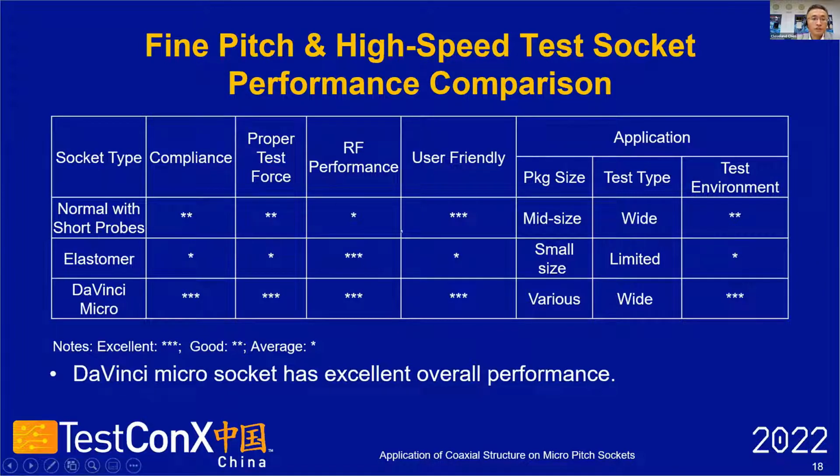Performance comparison for the fine pitch high speed device test sockets between the normal socket with shorter probes, conductive elastomer, and the DaVinci Micro. We can see the DaVinci Micro socket has overall excellent performance from the pin spring proper compliance, test force, application range, and RF performance, and maintainability, life, etc.